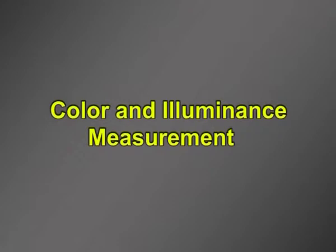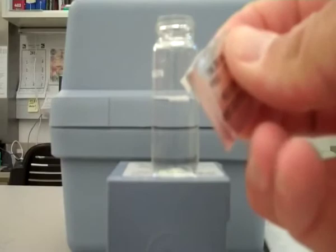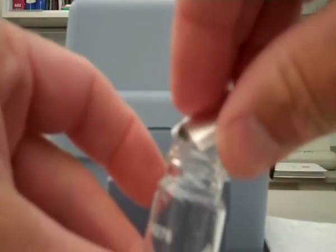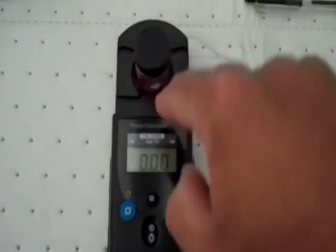Color and illuminance measurement. In many applications involving the measurement of color or the color temperature of self-emitting light sources, the same measurement geometry is used as for illuminance. Appropriate absolute calibration of the measuring system allows the illuminance of the reference plane in lux to be determined in addition to the colorimetric parameters. If the incident light is falling diffusely, this measurement requires the measuring system to have a field of view adapted to the cosine function.